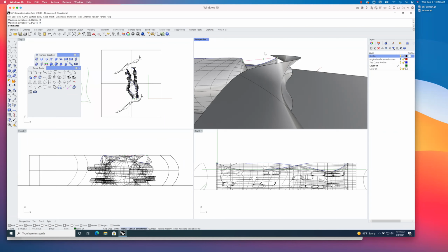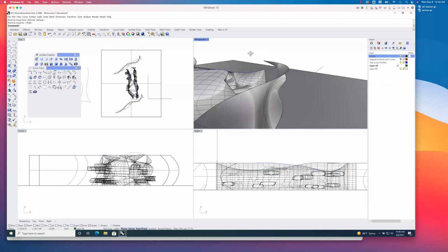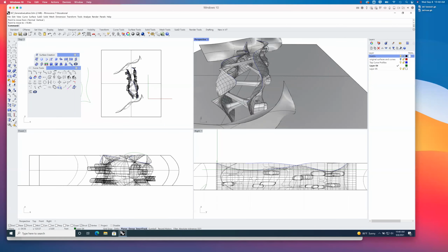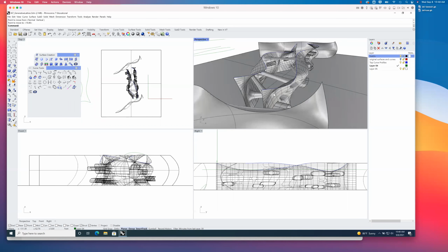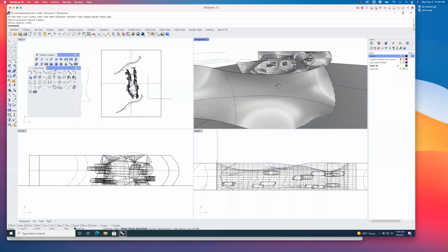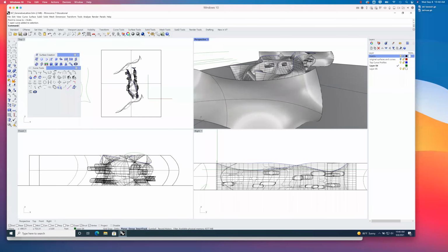Why not, right? And so that's going to let me kind of select just this point right here. It's similar to how we used a bow truss. I'm just going to move this up in Z. I'm just going to select that point. Oh yeah, look at that. All right. And so if I think about this, there's a lot of visual clutter on my screen, but I just made this curve, right? And now I'm going to sweep this curve along these 2 blue rails.